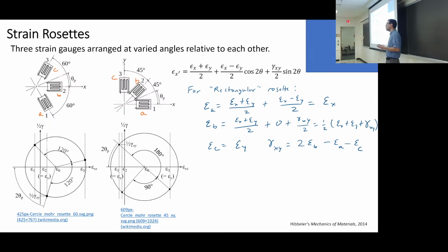And if I make a strain gauge too thick on top of it, I could be affecting the strain itself. So typically these strain gauges are supposed to be not very thick. We were just spending all this time telling you how plane strain is on thick substrates. Well, you want whatever you're measuring to have a high stiffness relative to the strain gauge itself. The strain gauge is just supposed to be along for the ride.